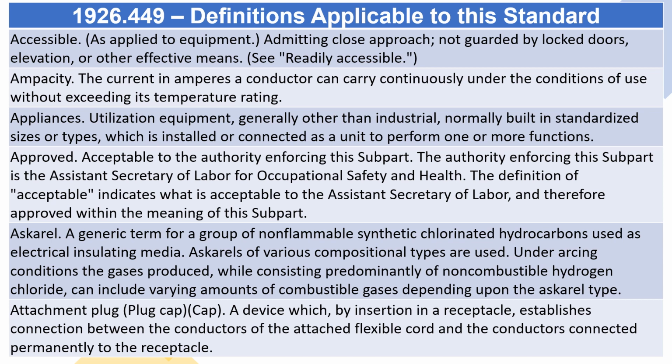Ascarel. A generic term for a group of non-flammable synthetic chlorinated hydrocarbons used as electrical insulating media. Ascarels of various compositional types are used. Under arcing conditions, the gases produced, while consisting predominantly of non-combustible hydrogen chloride, can include varying amounts of combustible gases depending upon the Ascarel type. Attachment plug, plug cap, cap: a device which, by insertion in a receptacle, establishes connection between the conductors of the attached flexible cord and the conductors connected permanently to the receptacle.